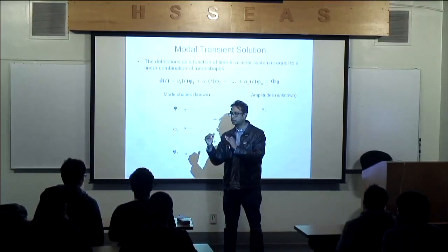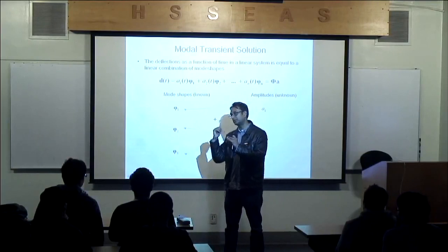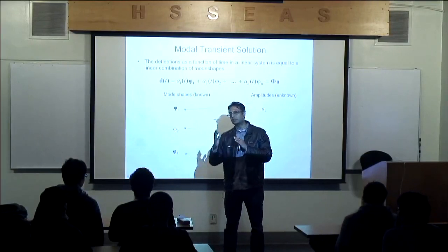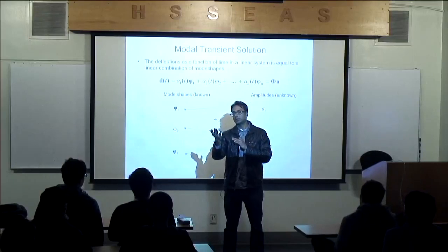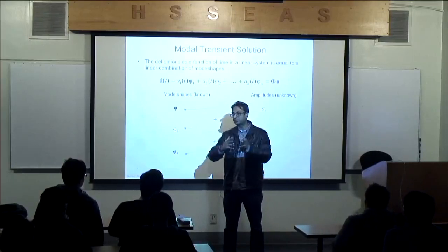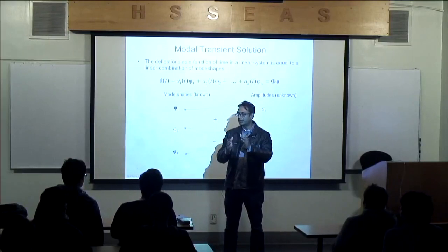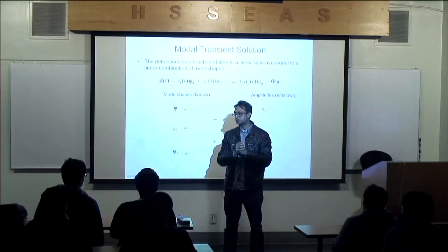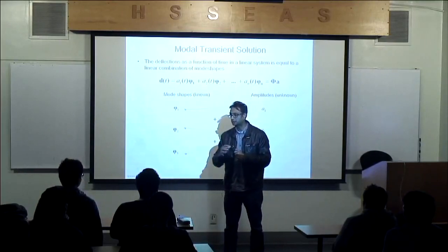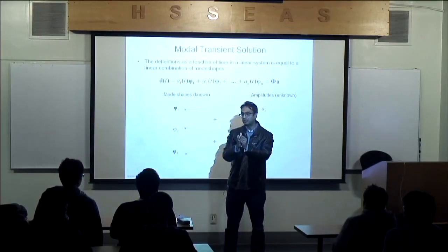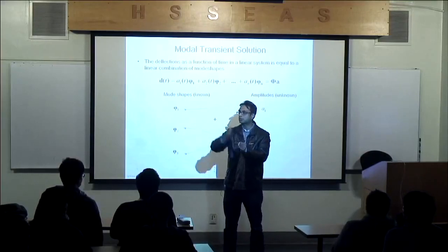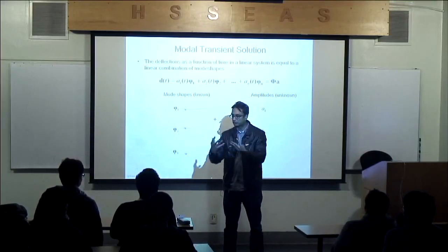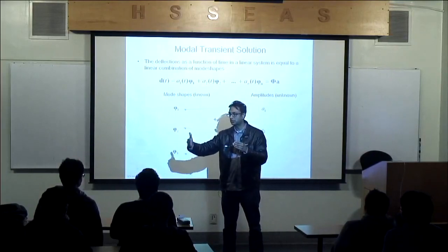And what I was trying to show you was the benefit of this approach. The benefit of this approach is that if I have a spacecraft or a wing or a very complicated piece that has millions of degrees of freedom, and I were to calculate how many mode shapes and how many eigenmodes I will have in that system. 1 million, say. How many frequencies will I have? 1 million, right? But what is relevant to the problem is only up to 200 hertz. Let's say that what's important to the problem is only up to 200 hertz. I don't care about anything above 200 hertz.